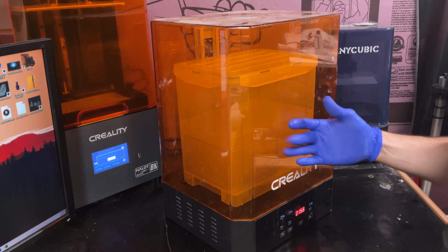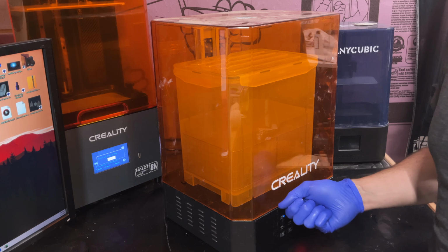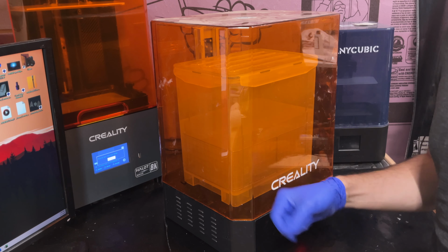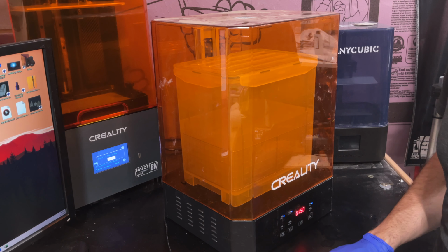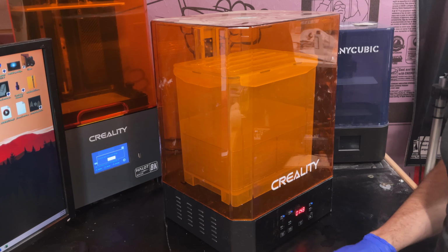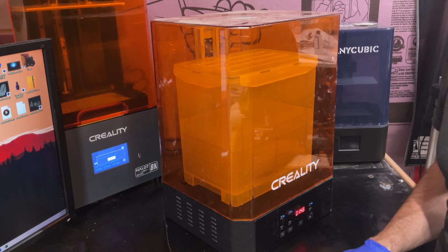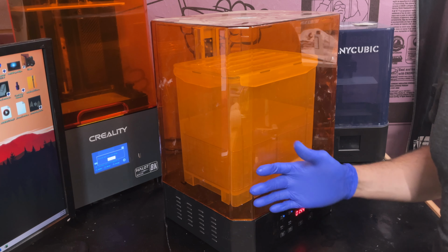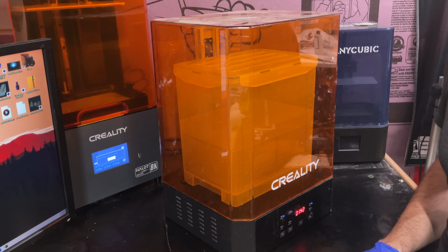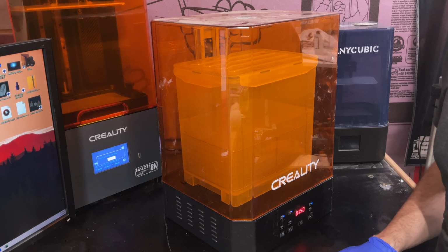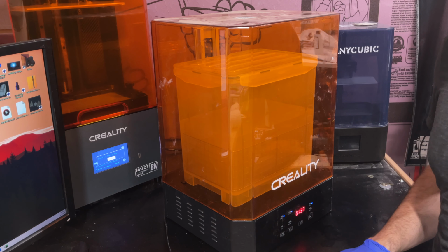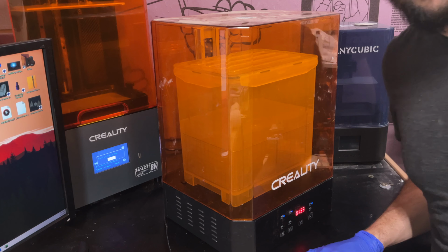If you don't have a wash machine, you can literally just use a tub with isopropyl alcohol in it, and a soft toothbrush, something like that, to scrub it clean. Works just as well. This is just hands off, automates the process a little bit. So I'll let this wash. I run it for about 2 minutes for this size part, and I'll come back to you, show you after it's washed, and then what the cure process looks like.